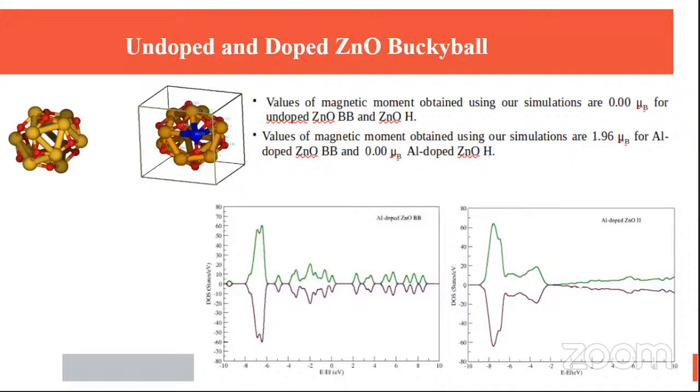So actually, this SIESTA has very good power. We just start from one unit cell, and automatically it starts running in the form of bulk. Generally, whenever I use that computational tool, I take one small primitive cell, and by studying the details of that material, I then use supercells if needed.